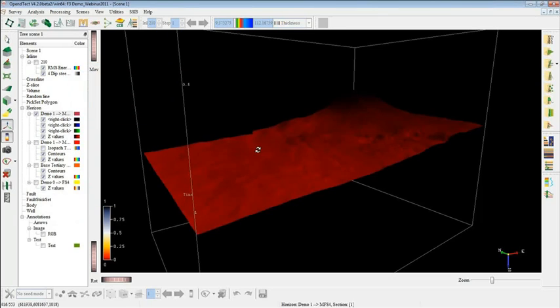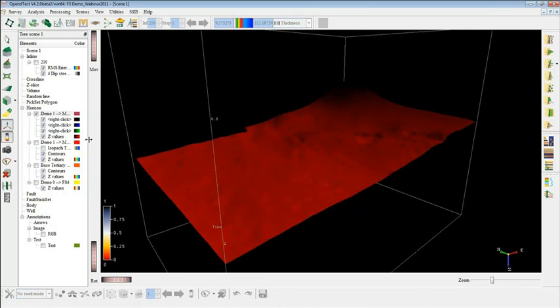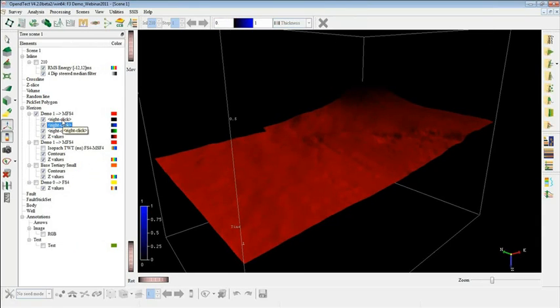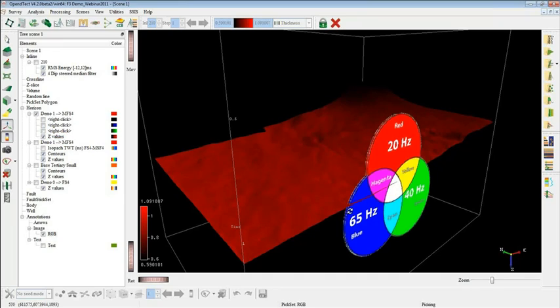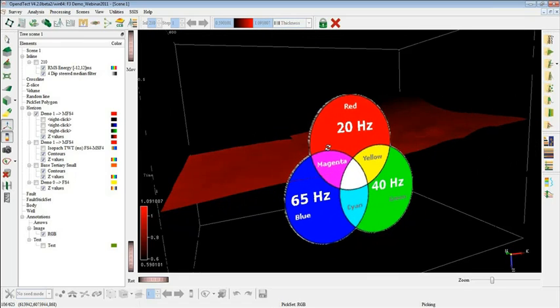In this way it is going to load a horizon with three major semi-transparent attributes along it, and they are by default blank. You need to load the data on it, and the fourth one is the alpha channel, which is transparency. I'm sorry, red channel is low frequency, green channel is intermediate frequency, and blue channel is higher frequency. So I need to load 3 attributes.